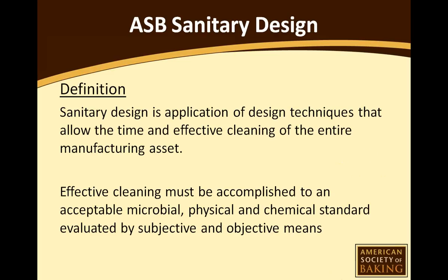By definition, sanitary design is the application of design techniques that allow the timely and effective cleaning of the entire manufacturing asset. Effective cleaning must be accomplished to an acceptable microbial, physical, and chemical standard evaluated by both subjective and objective means.